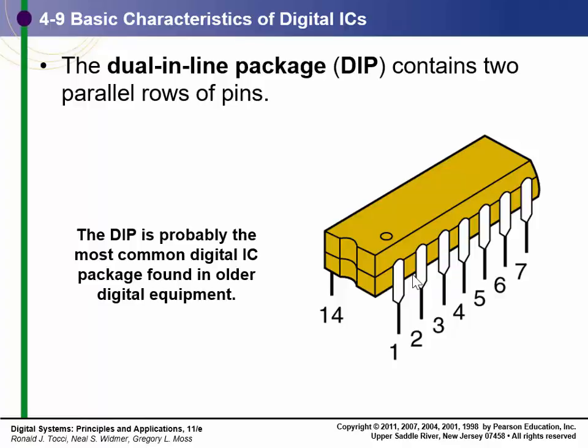You don't see that in typically produced products. If I opened up this laptop right here, I would probably see very few, if any, through-hole parts on that. They are just disappearing. And the reason is that they're too large. If you look at your cell phone, you won't see any through-hole components in that. But if you open up, say, your microwave oven at home, you might see some. So as electronics has gotten smaller, this technology has gone away.